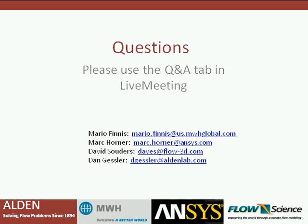Thanks. Next question. Have any of the presenters attempted to address issues with gas entrainment resulting from water passing over spillways, typically due to the velocity of the spilled water entering the pool at the bottom of the spillway? Dan, you mentioned that a little bit. Maybe you could take a first crack at that question. Yeah, we've used it qualitatively to look at air entrainment or gas entrainment going over a spillway and then see where it goes in the stilling basin subsequently. We have not quantitatively validated those calculations, though.